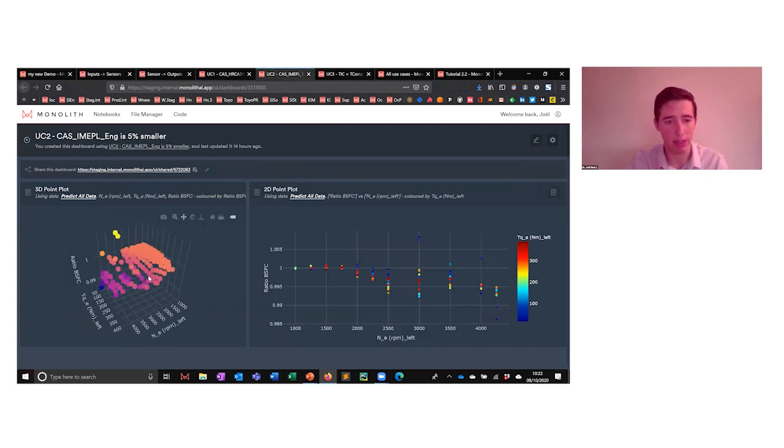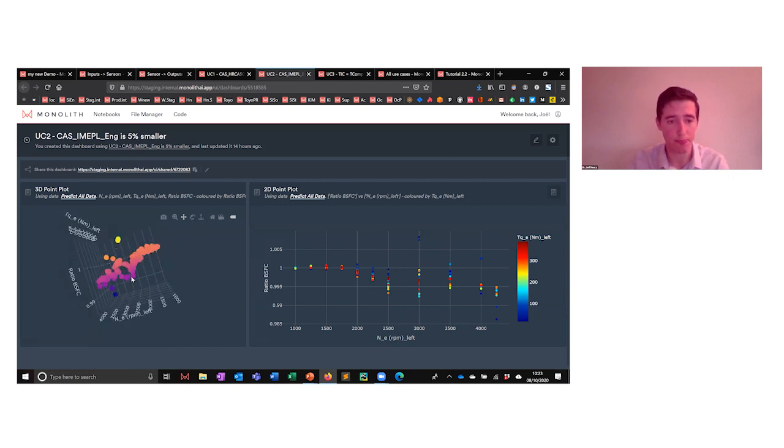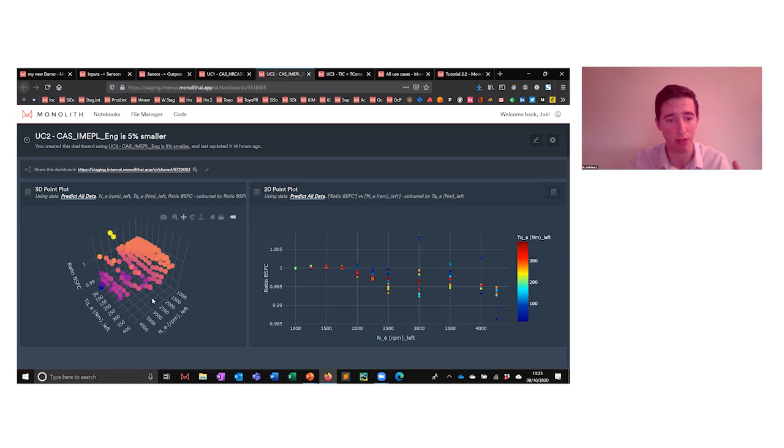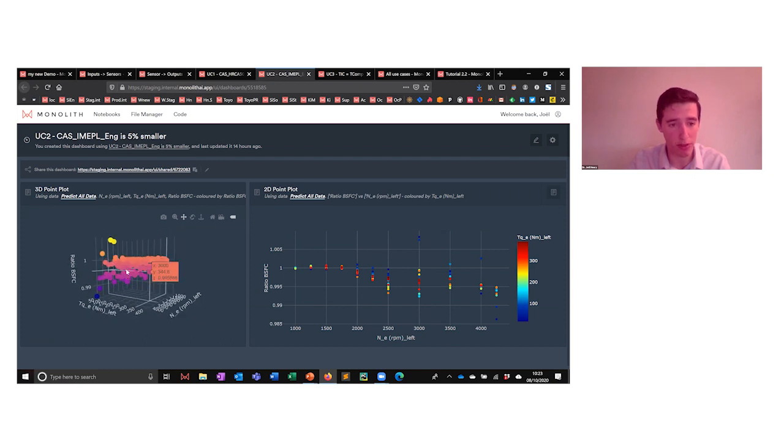So again, I'll go back to the platform, showing similar graphs. Here you can see a similar graph. We look again at the ratio. If we're below 1, it means that there would be a gain in fuel consumption. And it's quite interesting. You can see, for instance, that at low speed, there's no gain. You remain around 1 here. But as soon as you reach higher values of the speed, and especially for an average torque, you can get a decrease in the fuel consumption by up to 1%. And you can see it here again. You can go down to nearly 1%, or let's say around 0.5%.